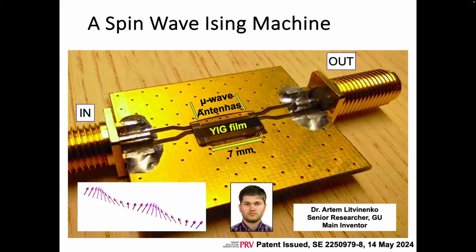Still some damping. So when they get injected here with a copper wire, they propagate 7 millimeters, and then they lose about 35 dB of power. So there's considerable damping if you compare with optical fibers, of course, where there's basically none across this distance and very little over kilometers of distances. So damping is an issue, but not a big problem. You can amplify that back easily.